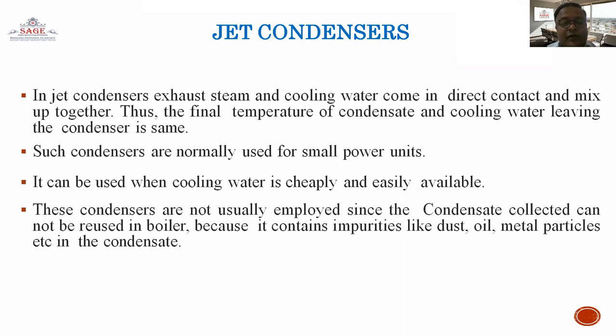These condensers are not usually employed since the condensate collected cannot be reused in the boiler, because it contains impurities like dust, oil, and metal particles.